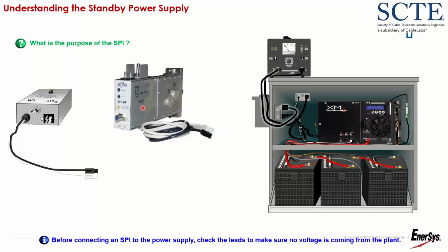It's called an SPI RF. It's really used where you don't have a tap close to the power supply. It has the power inserter built into it. You actually do send RF back to this device. The RF is extracted out of this F connector so you can connect it to your transponder. And you still have the Jones connector and the alt switch, but it's on the top, or I should say, the toggle switch. So just a little bit different guy.